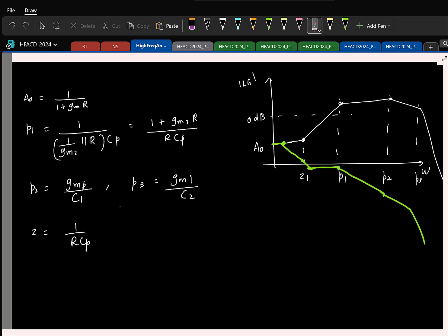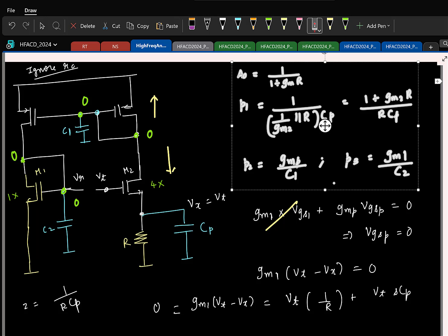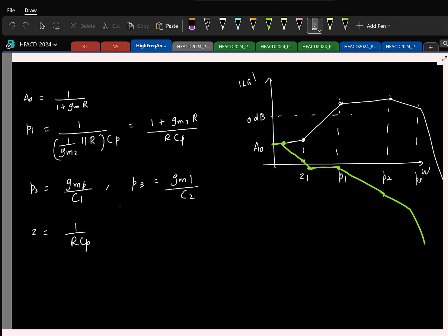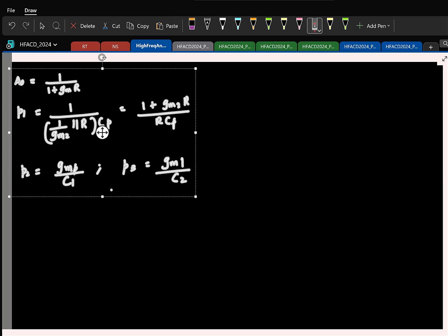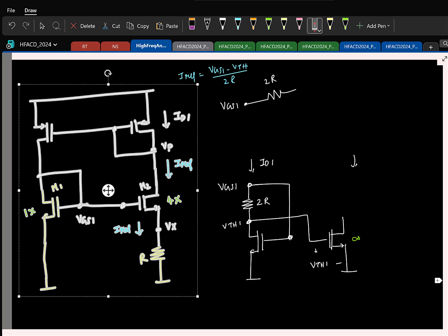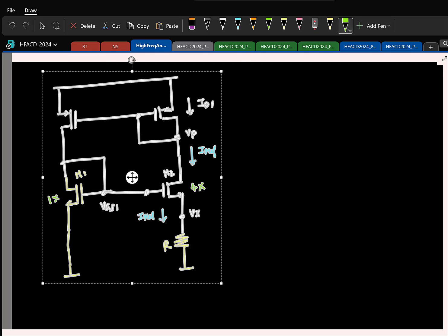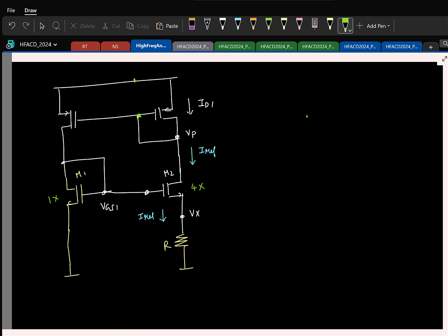So how would you do that? Instead of decreasing gm, a simpler thing: I can add a large capacitor, right? So you have to put an even larger capacitor that dominates CP. Let me take it to the next page. So you have to put an even larger capacitor on either of these two nodes, right? Only then can you actually get it.